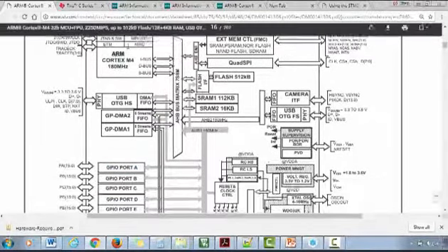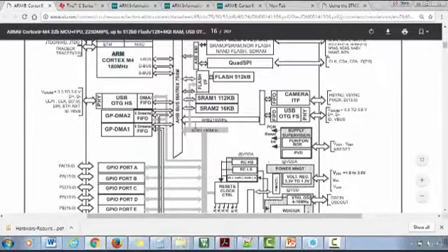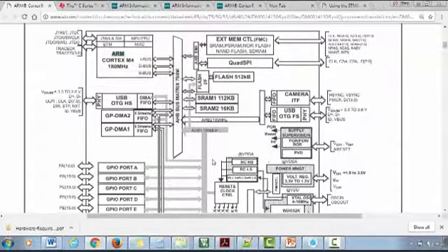So they both communicate over the AHB1 bus. That's true because it is connected to the AHB1 bus, and further from here to here the connection is actually through the system bus. So finally this AHB1 bus connects to the S-bus. And please remember that finally everybody should connect to the system bus through the bus matrix.